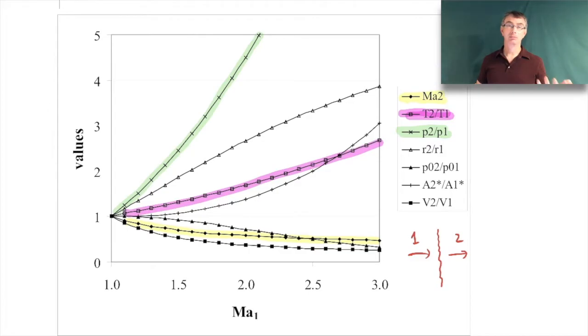So let's say you're standing there on a nice, 70-degree day, and then this shock wave comes past at a Mach number of 3. For a brief period of time, the temperature goes up by a factor of 2.5. So it goes up a lot. Okay, and it wouldn't be 70 times 2.5. You should do it in degrees Rankine, right? So you need to use absolute temperatures, so it's either Kelvin or degrees Rankine. It's a significant change in temperature.